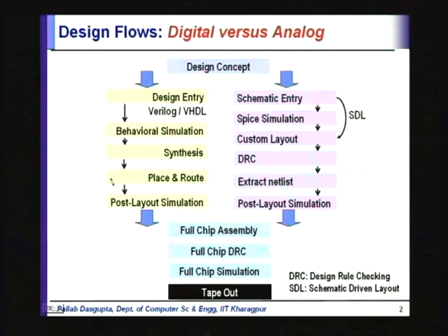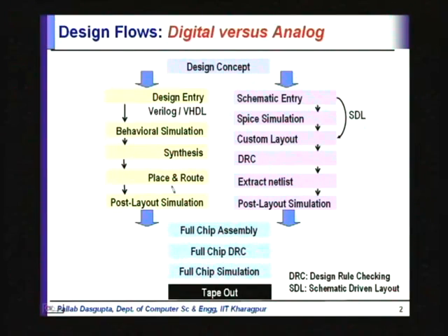We just geometrically place the different blocks on the floor of the chip, and then routing means that we have to interconnect these blocks to get the complete chip. Okay? And often this routing is done across the parts which are designed by separate designers. So, again that is a non-trivial task, and the shape of the different blocks, their placements and the routing is all an integral problem, because if you place them badly, then you will not be able to route them properly. If you place them properly, you are able to reduce the amount of interconnects to connect them.